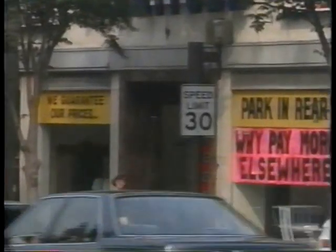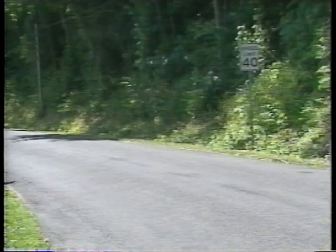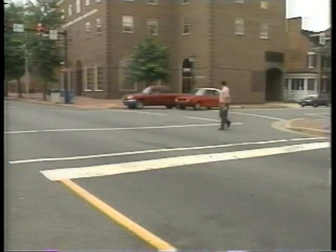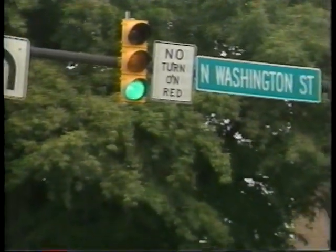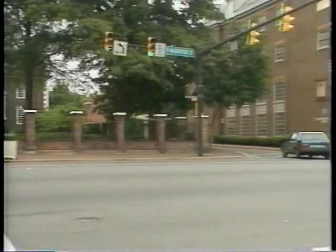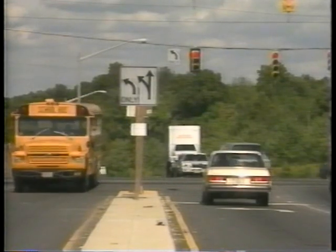These signs are put up under 2 conditions. First, whenever the speed limit changes. Second, additional signs should be put up if drivers need to be reminded of the speed limit. Signs for drivers at arterial road intersections may clarify signal control. They include left on green arrow only, stop here on red, and do not block intersection. These signs should be put on the appropriate signal head. These intersections also have lane use signs.